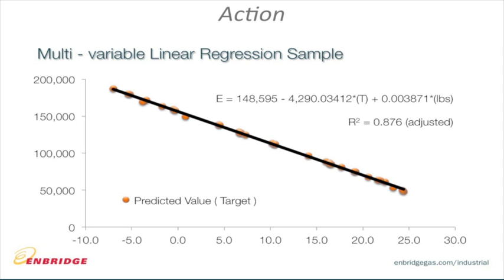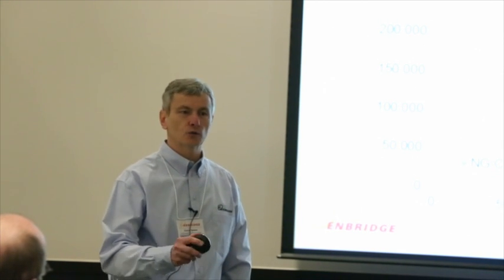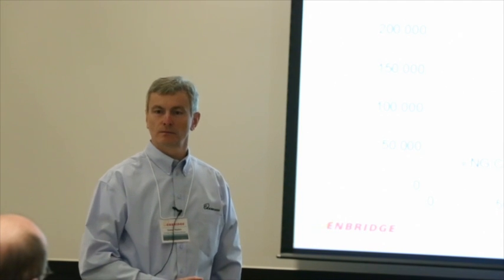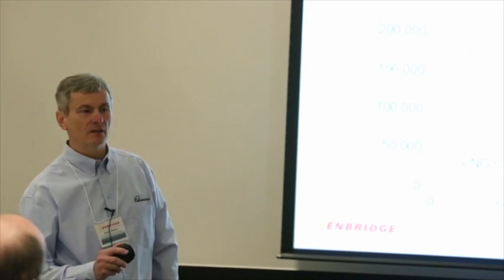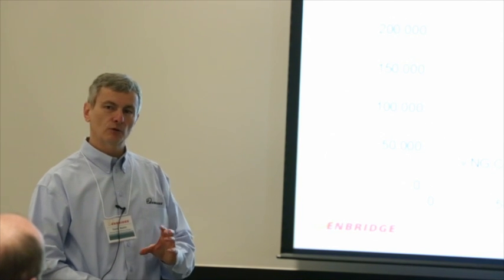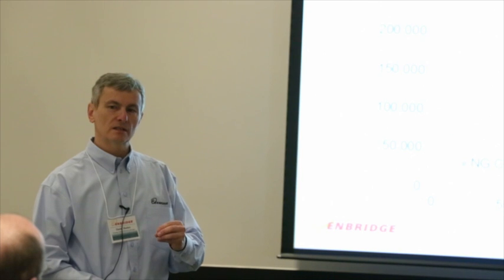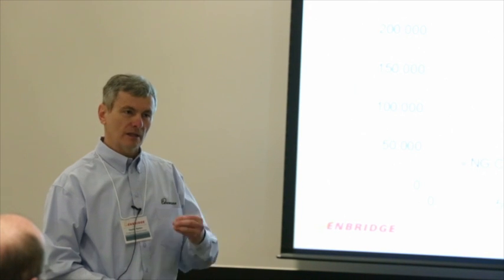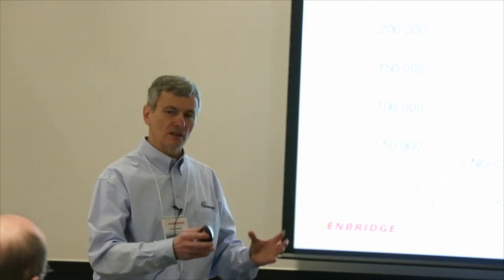So that tells you, I better load that paint line as much as I can and run it for all it's worth and then take 2 days off, rather than run it for 5 days, 3 hours every day. Because the losses out of this paint line are horrendous. And this is not a bad paint line. This is a regular paint line. This is nothing special. So that's how you have to interpret energy management. What is this information telling me for my process? I know my process. Mathematics just helps me put it into perspective.